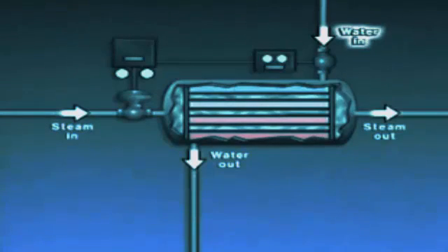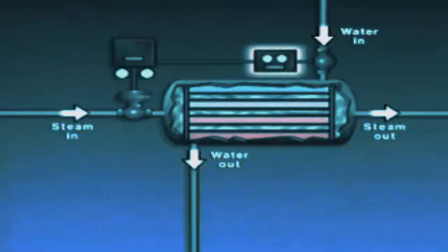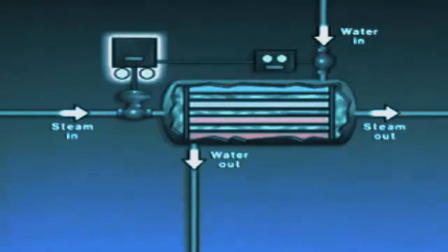If the temperature of the water entering the heater changes, the primary element in the system, in this case, a temperature-sensing bulb, detects the change in temperature and changes the signal that it sends to a transmitter. The transmitter measures the signal from the temperature-sensing bulb and sends a proportional signal to a controller. The controller measures the signal from the transmitter and compares it to set point.